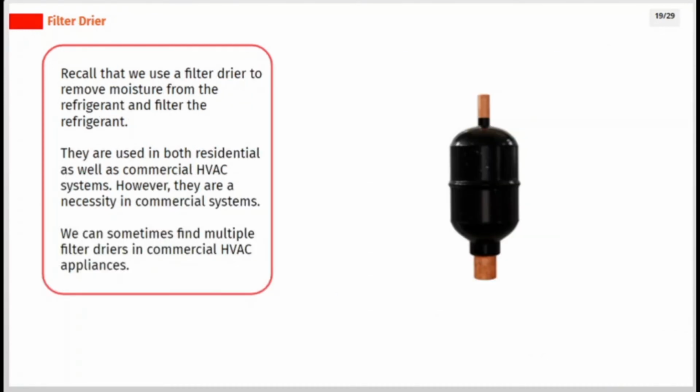Recall that we use a filter dryer to remove moisture from the refrigerant and filter the refrigerant. They are used in both residential as well as commercial HVAC systems. However, they are a necessity in commercial systems. We can sometimes find multiple filter dryers in commercial HVAC appliances.